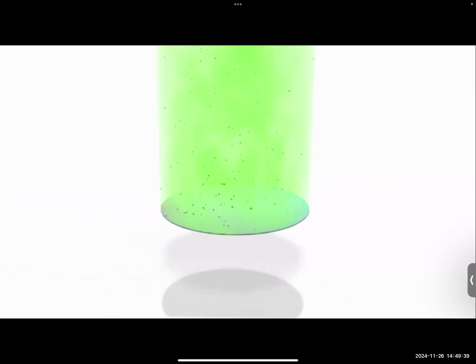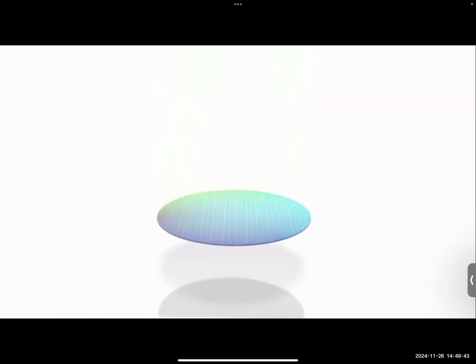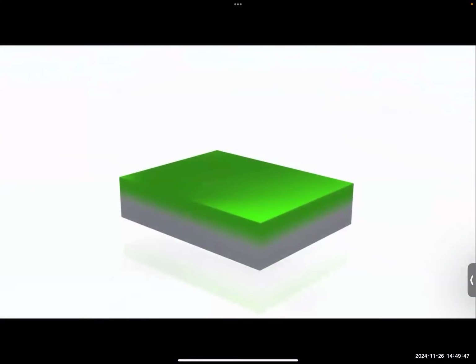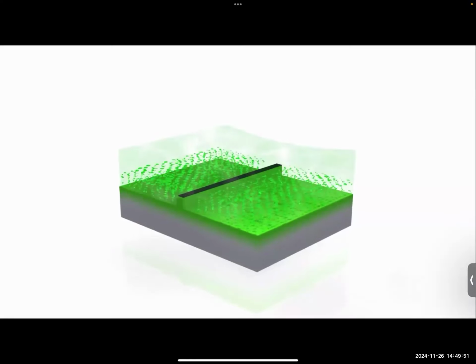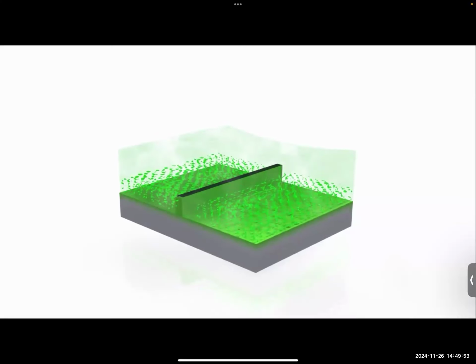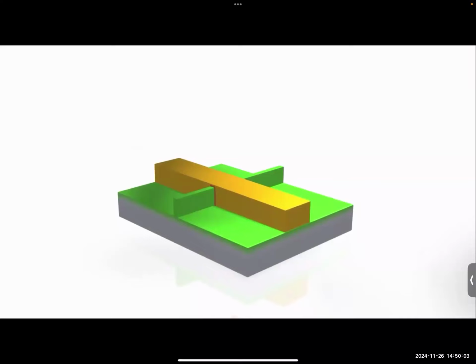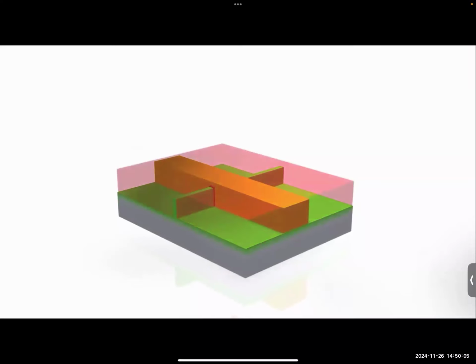After you create that pattern, this is again doping. You start with a type of silicon wafer, but on top of it, you might need other types of doping, like P, N, P, one doping inside another doping inside another doping. So you keep doping over and over again. Then there's another chemical process called etching. You use different chemicals; it's kind of like you draw something and you erase something. You erase with etching, you draw with patterning in lithography. The light-based patterning is called lithography.